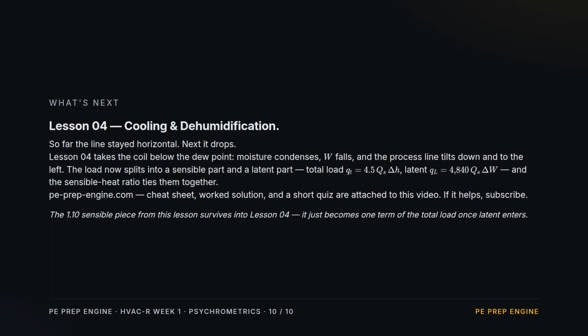Next up, Lesson 4, Cooling and Dehumidification. Drop the coil below the dew point and moisture condenses. The humidity ratio falls and the line tilts down. The load splits into sensible and latent, tied together by the sensible heat ratio.